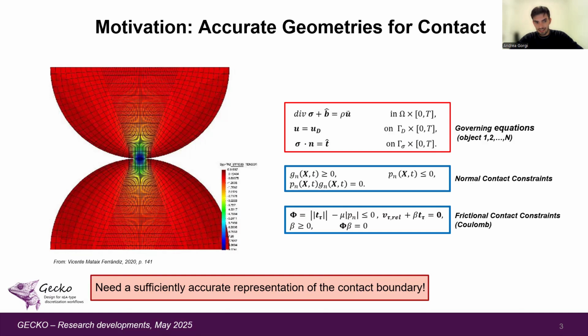Well, this is exactly what led us to the question if there was a solution or a way to have this geometrical accuracy without the introduction of this complexity in the numerical simulation, to achieve accurate solutions with lower costs in the numerical simulations. Well, a first answer was the use of isogeometric analysis, which is exactly the technique to create those nonlinear elements that are able to correctly capture the features of our geometry, even with coarse meshes.